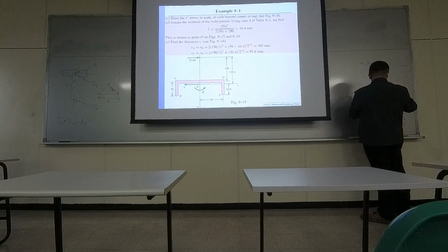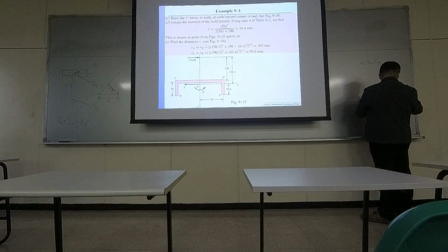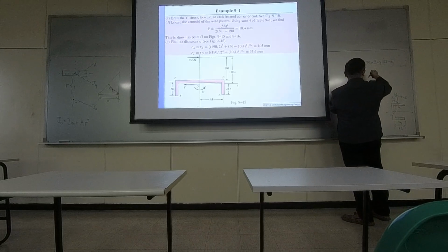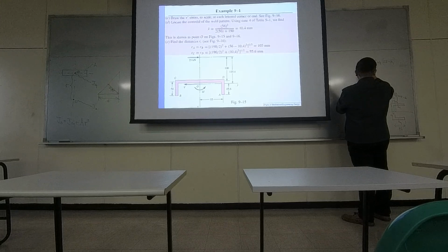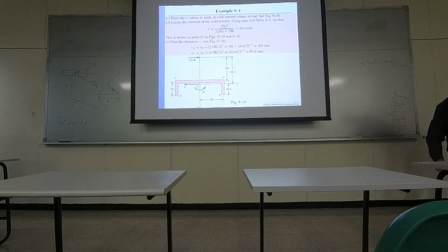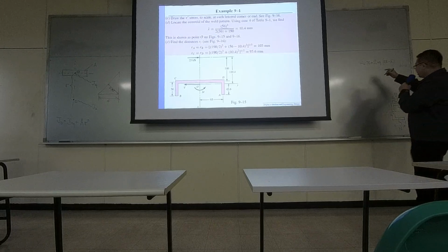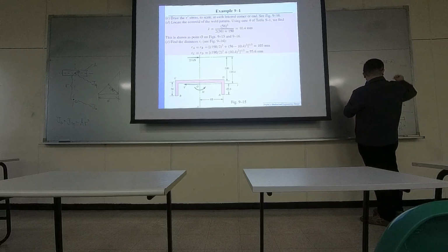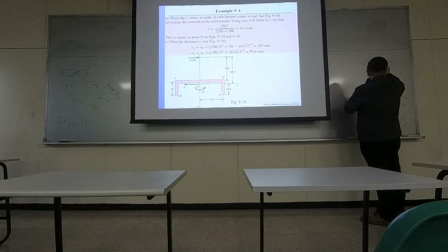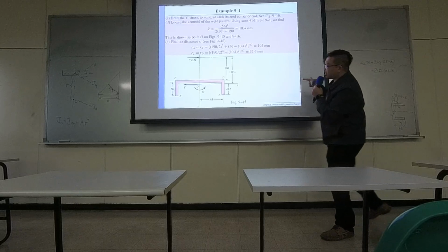That distance would be half of the 56, or 28, minus X bar. And W is proportional to the length, so you can use the total length right here to represent W1. That would be 56. So 2 times 56, times 28 minus X bar. And here is 190.